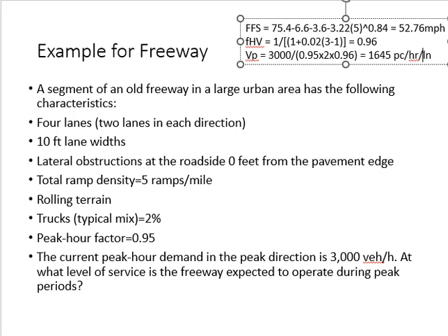Free flow speed. This is one speed. But do we always have free flow speed on the road? First of all, I need to find out whether this is the speed on the road when the flow rate is this much. And this depends upon the speed flow curve.